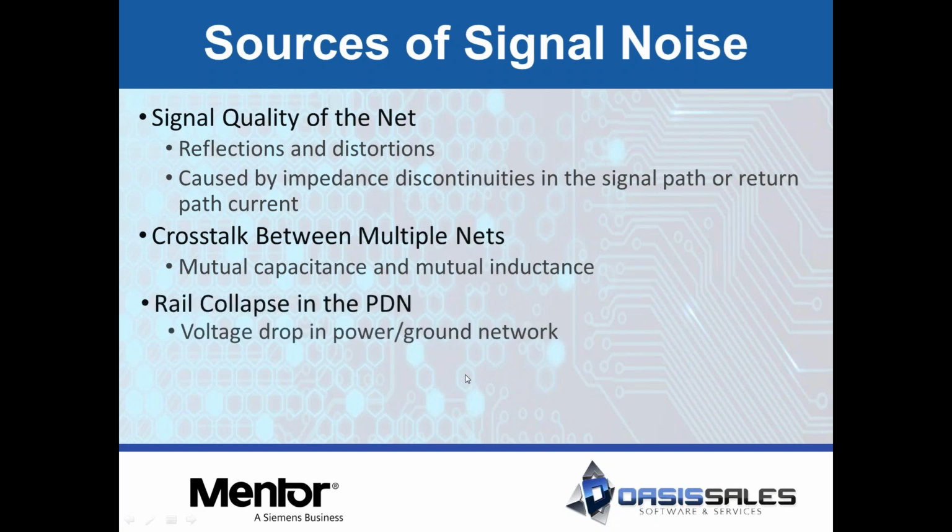But that's, hopefully everyone understands that. Another issue that's becoming more and more prevalent today is low power devices. More and more devices are running at 1.8 volts, 3.3 volts, and you can start having issues with voltage drop in your power rails due to switching devices if you're not supplying enough current to those items. And I'm going to talk about a tool at the end that can assist in this area.